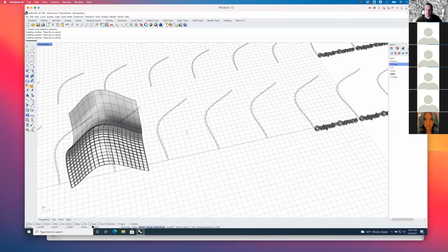We have routers that do similar things using CNC technology, just like a laser cutter. In fact, we have a larger CNC router in our shops here at school that can do this, out of plywood and maybe even non-ferrous metals, really soft aluminum alloys, if we're spritzing it to cool off the tool so it doesn't get too hot. We also do plastics and acrylics and things like that.